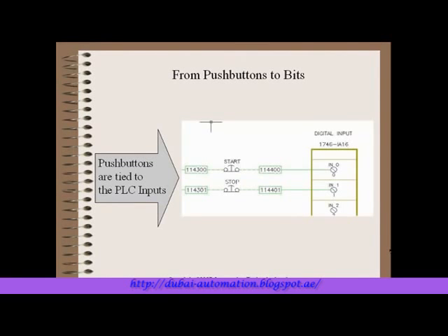So what's the difference between the PLC and the regular hardwired option? With hardwired, you saw we take our push buttons directly to a relay, and it acts directly upon that relay. With the PLC, our start button comes into an input card. It's wired directly into cards that interface directly to the processor through a rack or some other means.